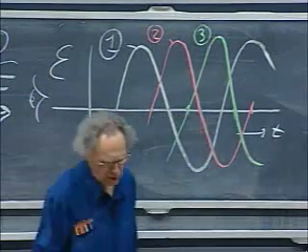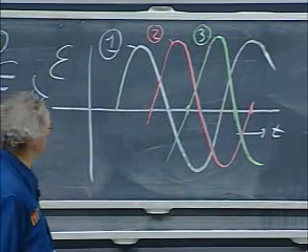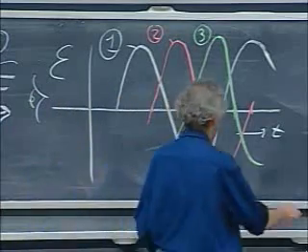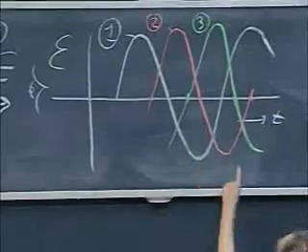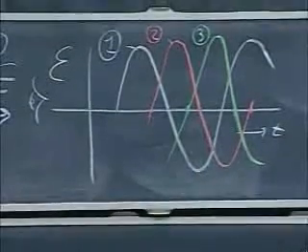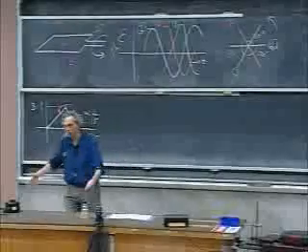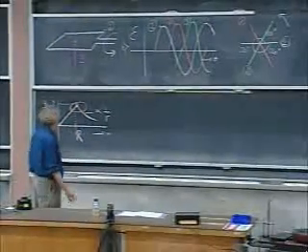And a 3-phase current can produce a rotating magnetic field. We will make one for you, but I'll first explain to you how that works. So if the period of number 1 is 60 Hertz, then the period of number 2 is also 60 Hertz, and number 3 is also 60 Hertz, but they're just offset in terms of the phase angle.